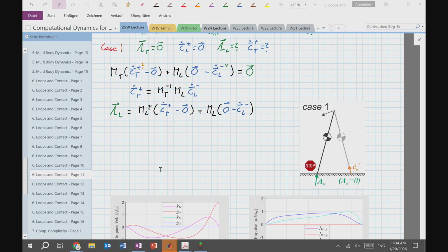But I would build this up step by step. Start thinking about rolling on a flat surface, then think about how things change if I roll on a circular surface, and then maybe go back. Whatever equations you derive, of course, if you set one of the two radii to infinity, you should get the equations for rolling on a flat surface. So that's always a good way of checking your assumptions. And if you make one radius go towards 0, what does that mean? You end up with a pin joint. So these are always good checks.